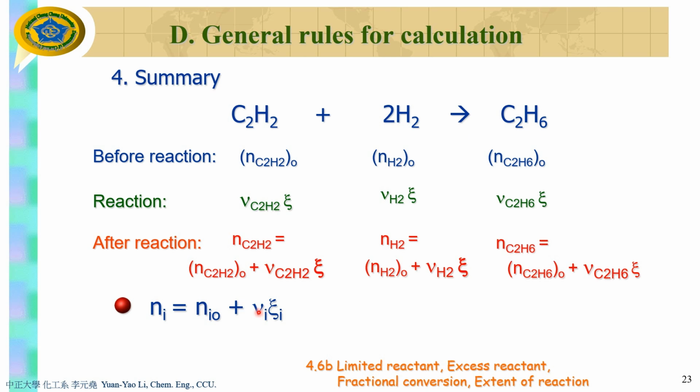And you might say, well, Professor, the general balance equation tells us there are 5 terms. Where is accumulation? Well, in all these cases, we always talk about steady state. We don't have any accumulation term. So again, output equals input plus generation or consumption.